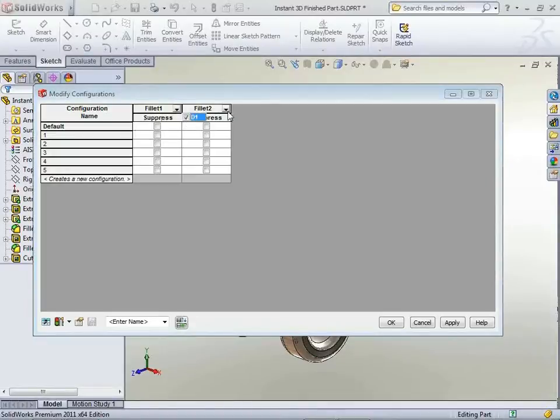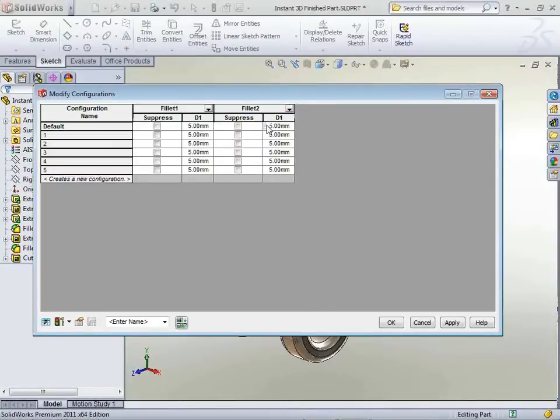You can also manage the dimensions on each of these configuration features on the configurations. So for example, I can have here 5.25, and you will notice that as we are in Excel, if I select two cells here and simply click this little green button, the plus is going to show up, and drag it all the way down, it will automatically increment every single cell. Let's do that again. This time I'm going to change this to 5.5. It's a quick way of doing things.